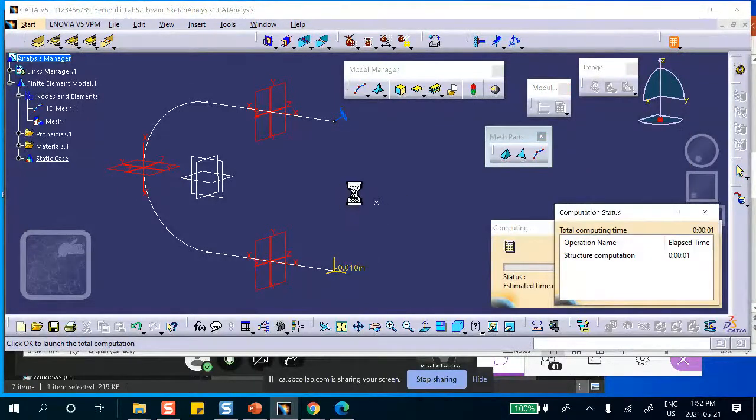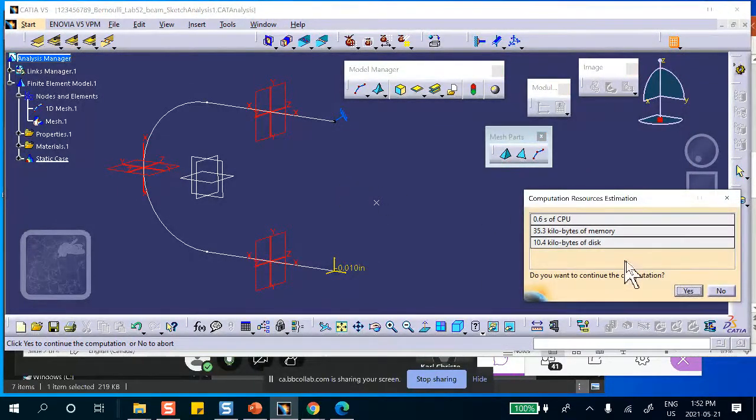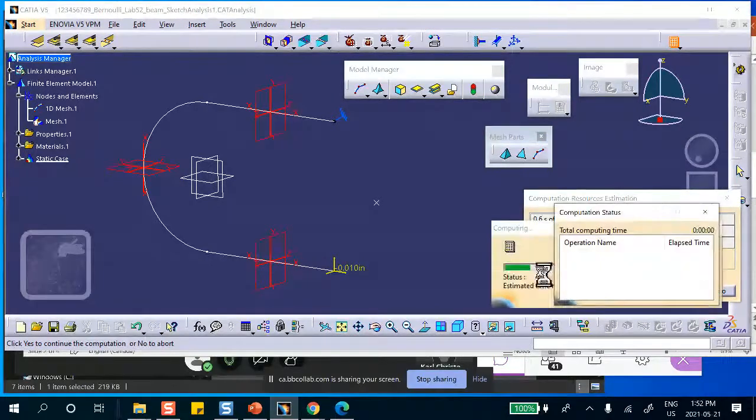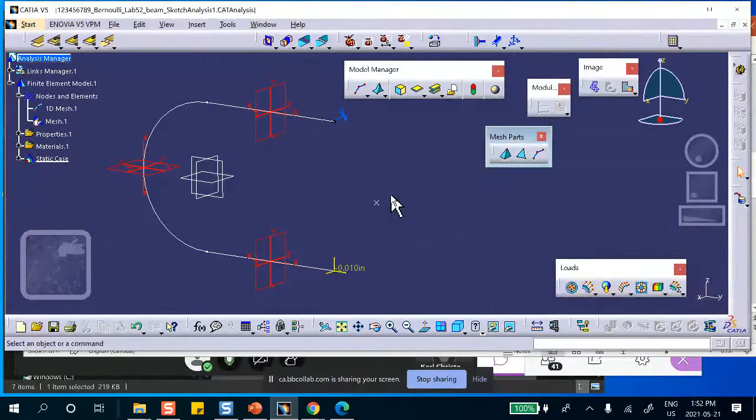and you run it. A couple of comments here. I've said these things many, many times, but I'll say it again. Notice that the C-clamp problem that we solved was a three-dimensional object. It had a hole up there, and the hole was clamped. Well, you can't do details like that on beams. Beams basically ignore the hole and say, this is it.